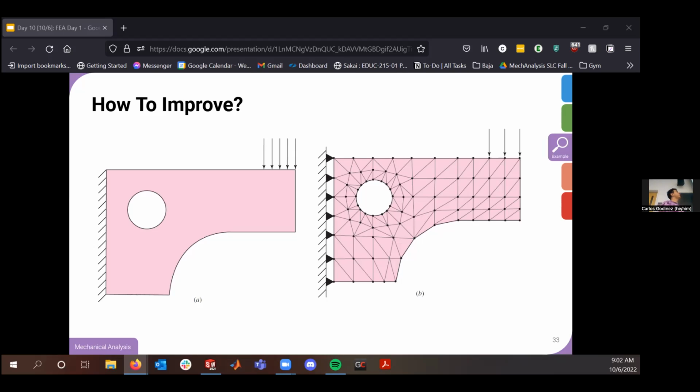For a simple case like this, you're not sacrificing that much by just saying, I don't want to think about this, I'll have a mesh size of 0.1 millimeters and a 20,000 element model. It probably won't take that long to solve, especially with a pretty simple loading case and relatively simple geometry.